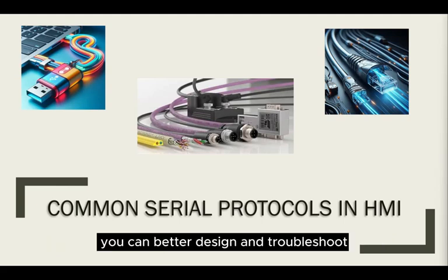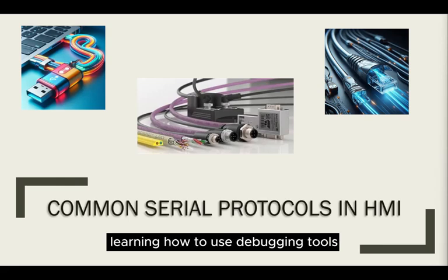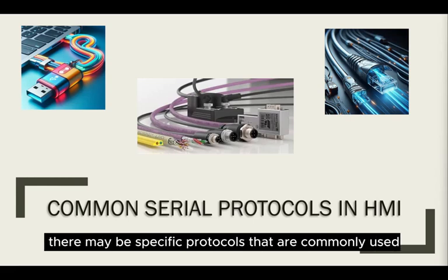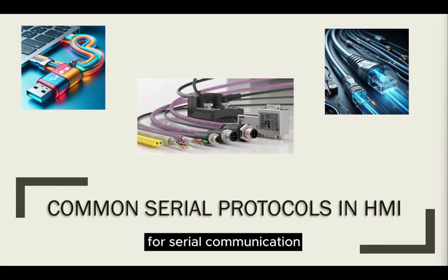You can better design and troubleshoot your HMI systems. Also, learning how to use debugging tools to troubleshoot communication issues can save a lot of time. Depending on the industry, there may be specific protocols that are commonly used. For example, Modbus is widely used in industrial applications for serial communication.